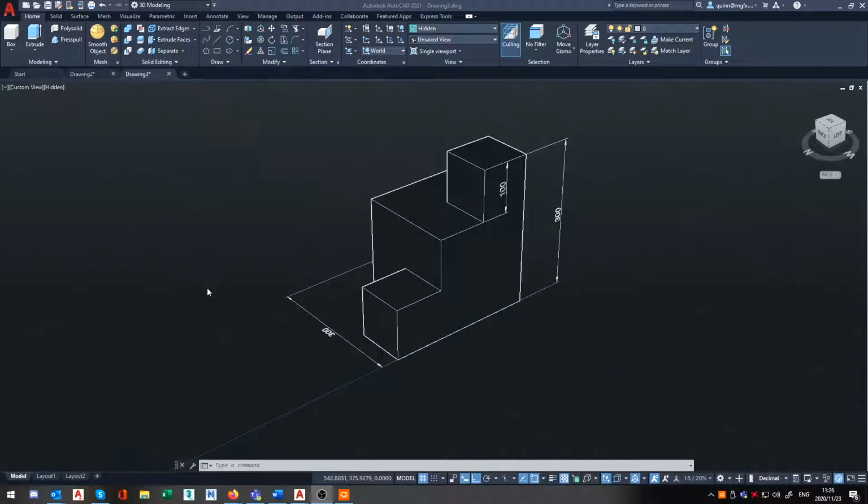In some of my previous blogs, I've talked about manipulating the UCS. So I thought maybe in this one I'd give you a bit of a primer as to how to do this to try and get the most out of drawing. Unlike in Inventor and Fusion, where we've got our set planes that we can work on, in AutoCAD we have to manipulate our UCS, our user coordinate system, in order to draw or change the plane that we're working on.